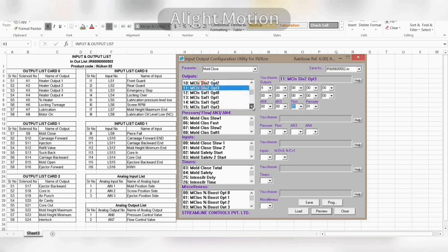Accordingly, mold close safety 1 option 0: output number 9 and pressure 0 1 and flow 0 1 enable. Same way, mold close safety 1 options 1, 2 and 3: output number 9 and pressure 0 1 and flow 0 1 enable in each.